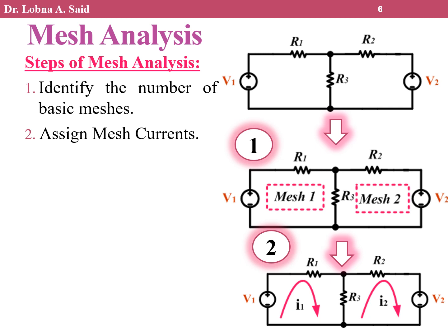If you look closely, you will see that I assigned the two mesh currents oriented clockwise. As we agreed, I am completely free to take my loop direction clockwise or counterclockwise. In nodal analysis, as I told you, we assumed at each node that the currents are leaving and repeated this assumption at the next node. Here we are going to do KVL. In nodal analysis we did KCL to get voltage. Here we will do KVL to get current.